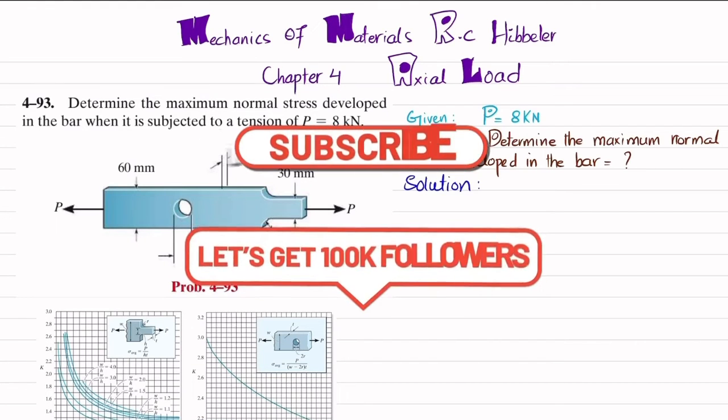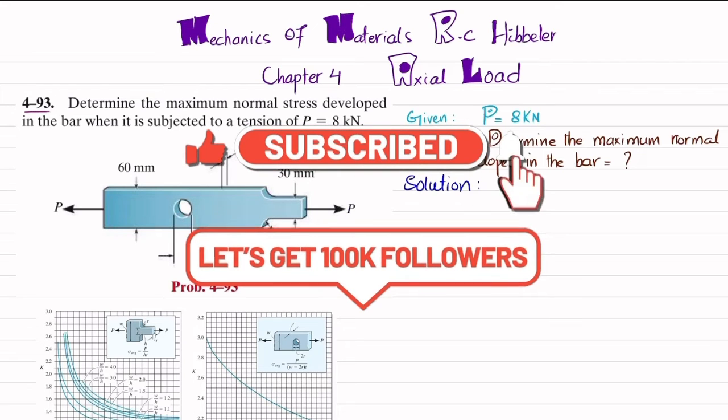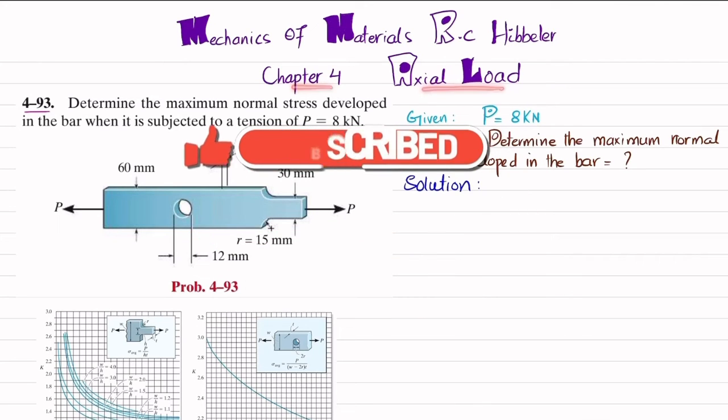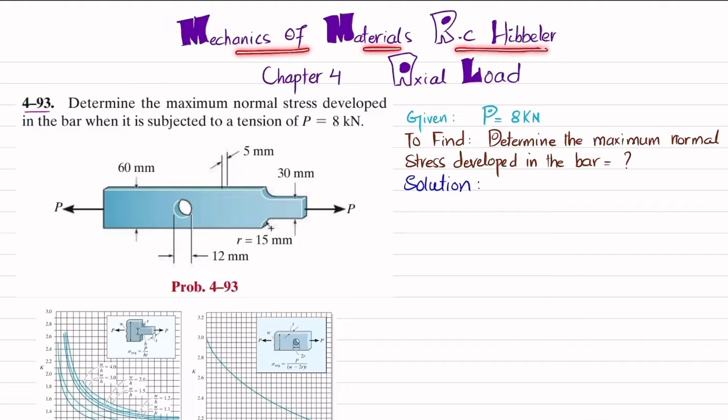Welcome back. In this video, we are going to solve problem 4-93 that is taken from chapter number 4, axial load, and the book name is Mechanics of Materials by R.C. Hibbeler. So the statement is: determine the maximum normal stress developed in the bar when it is subjected to a tension of 8 kilonewton. So this is the bar you can see which is subjected to an axial load of 8 kilonewton. There is a hole in this bar as well as a fillet. So due to this hole and this fillet, there will be a maximum stress at this portion which is called stress concentration. So we have to determine that maximum normal stress developed in this bar.